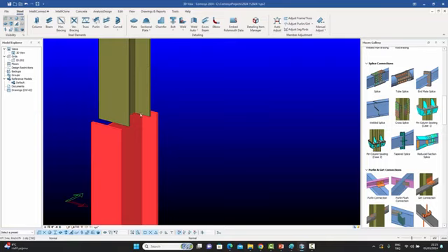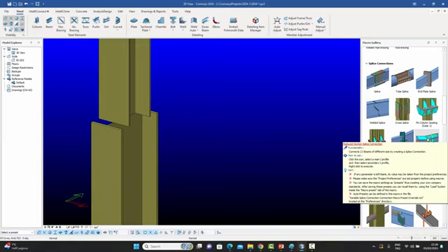That makes using the classical splices, where you can use a few filler plates of maybe a few millimeters thickness to cover for the changing height, very difficult, because the change in the size of the two sections is significant, and other methods can be used to connect. In this version we have provided one such solution for you, which is very useful and very handy.